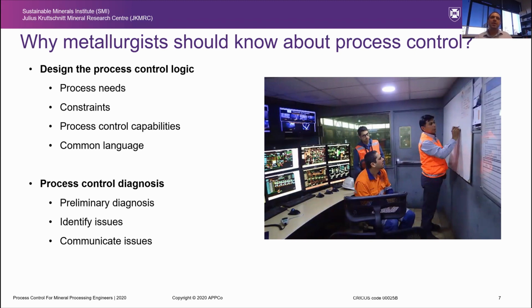The other aspect is when you're trying to diagnose a process. Having a good understanding of process control is going to help you identify, when you face issues while the process is running, whether they come from the process control, and you can do a preliminary diagnosis and identify where exactly the issue is. And because you now have a common language as well, you would be able to communicate that issue properly with the control engineers to try to resolve it.